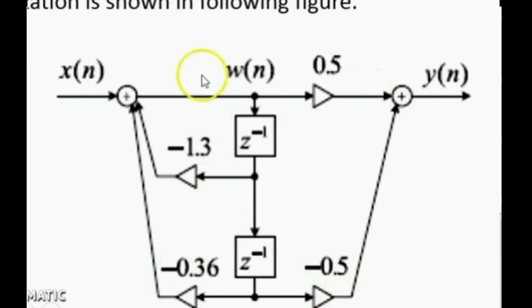It is considered a canonical structure because it offers an advantage in terms of memory usage and has potential for pipelining in floating point implementation. Whereas direct form 1 is advantageous for fixed point implementations, to avoid potential overflow issues in the intermediate calculations.